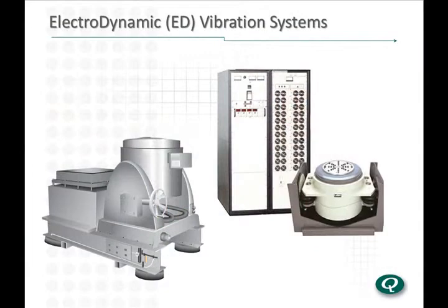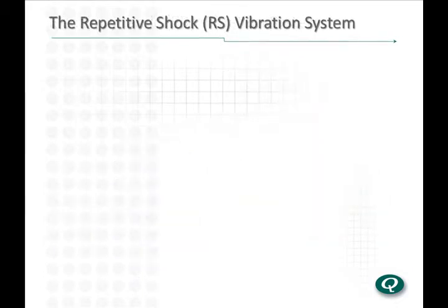Typically, reliability engineers think of electrodynamic or ED vibration systems for delivering vibration stress. The stresses and fatigue induced by ED shaker vibration are well understood. In highly accelerated life testing, repetitive shock vibration is used.